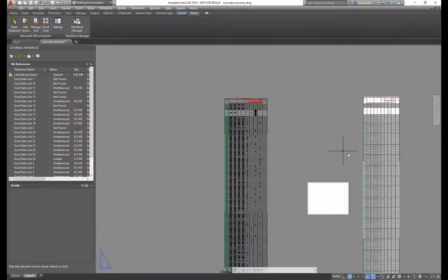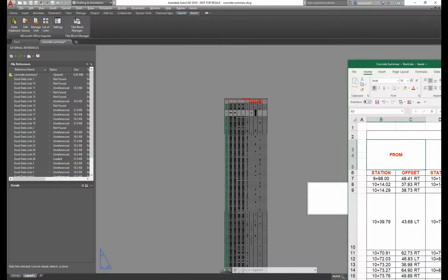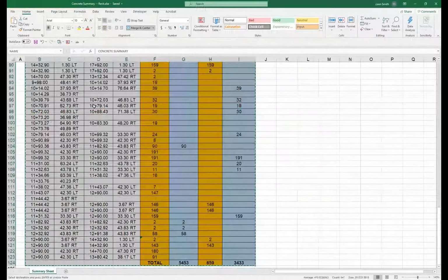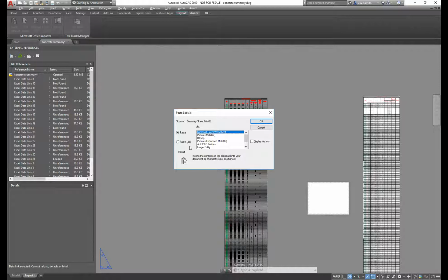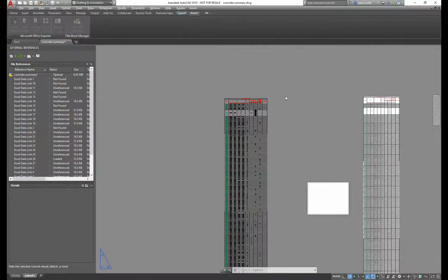I mean, all right. So let's go to that spreadsheet. This is just one I stumbled on because it's a nice sample file in our Revit software. So you come over here, it's a similar spreadsheet. You select what you want, you copy it to your clipboard, and let's go over here. What am I doing? A paste special. I'm gonna do paste a link, AutoCAD entities, and I'm gonna say okie dokie. All right, so this is kind of like medium slow pasting.